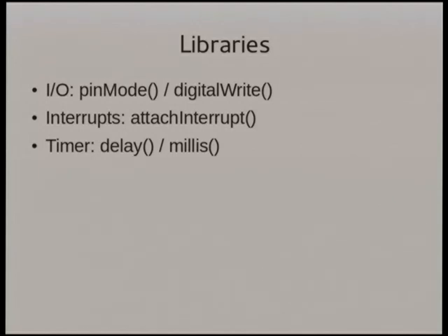For interrupts, something like attachInterrupt, say when pin 2 is rising, I want to schedule an interrupt to this function. With timers, it's not really the way that when I was using Arduino I was thinking about it, but really it is. There's a clock in the background that's counting along, and when you call the millis function, it just grabs the current value of that clock. And similarly with delay, it just sets up a thing that can wait for the clock to advance the right amount of time.